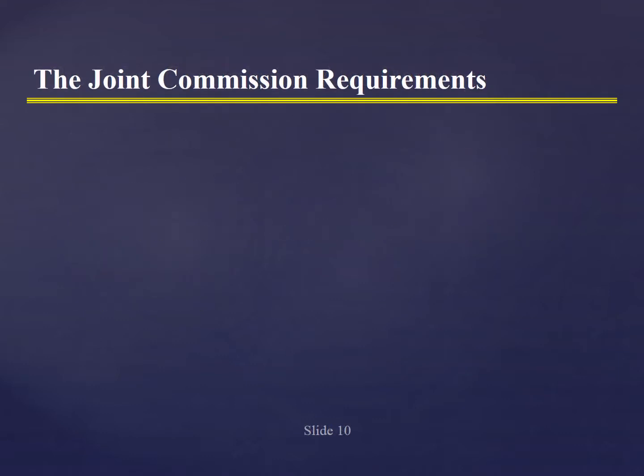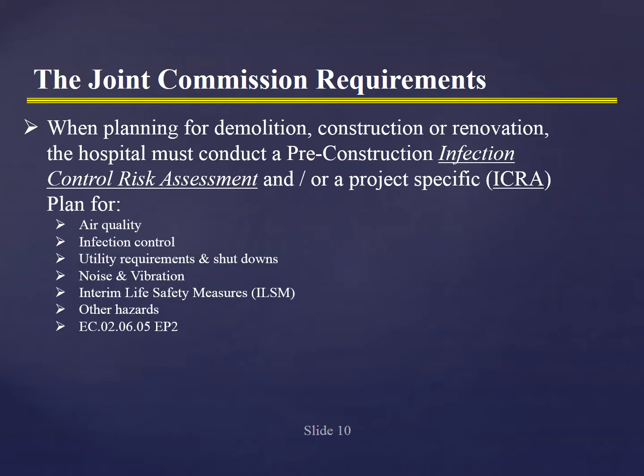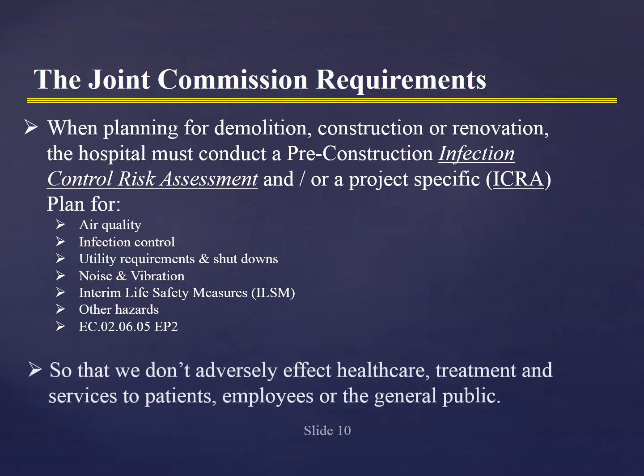There's language, and that language is when planning for demolition, construction, or renovation, the hospital must, very strong, must conduct a pre-construction infection control risk assessment and/or a project-specific ICRA. And those plans must be for air quality, infection control, utility requirements and shutdowns, noise and vibration, life safety measures, other hazards, and then again points back to EC 02.06.05, EP2. Now, again, when you look at this, it says demolition, construction, and renovation. But believe me, this is expanding, and it's not going to be long before this language is going to be very specific to maintenance operations. But they could be applied.